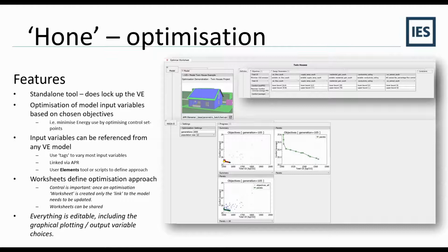So what you then have is eventually, in the green line you see in front of you, a Pareto curve where the optimums will show themselves against the study objectives. So you might, for example, very quickly set up a study that has 10,000 simulations, but as the study takes place, the genetic algorithm understands that maybe 50% of them won't achieve what you're looking for, and so will delete them. Therefore, not only does it bring you back more of the relevant results, but it also speeds up the overall process dramatically. The optimization methodology really follows three key components.